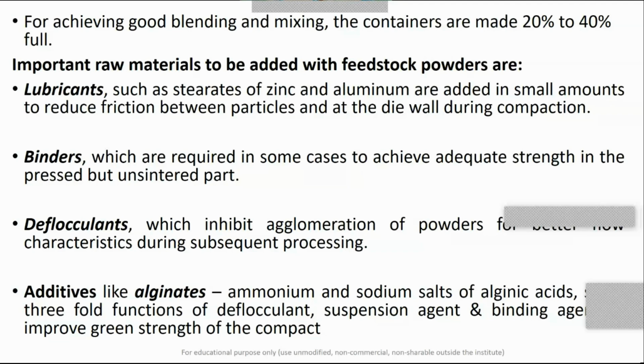I have told you what the effect of friction in the powder particles is. So it will help the flowability. It increases the flowability in the die cavity. Also, during the compaction process, there is always a very small clear gap between the die and the punch, and some automatic lubrication is always required to reduce the wear and tear of the die and punch. So this solid type of lubricant is the preferred one, and zinc stearate and aluminium stearate are the top choice.